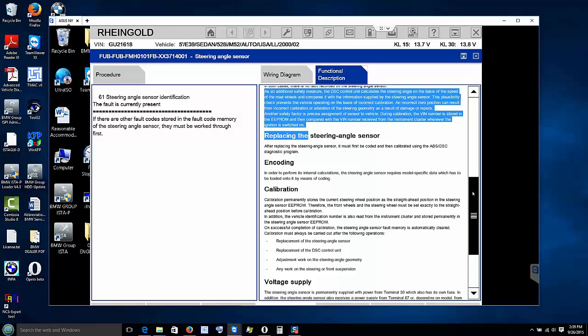The numbers are close, I understand, but I'm just saying because he went through everything and we look at it, and when you turn the steering, you can see the steering angle and everything moving. So we know we get a reading from that. If it wasn't getting any reading, then we could say, well, the sensor is bad. Right? And you went through the programming and then it's still telling you that something is wrong with the sensor.